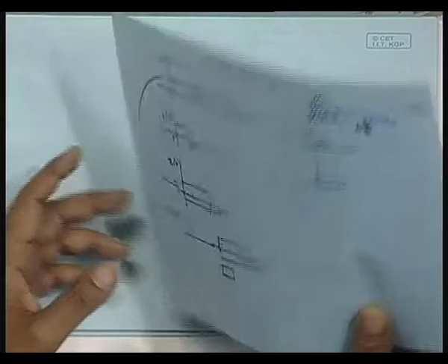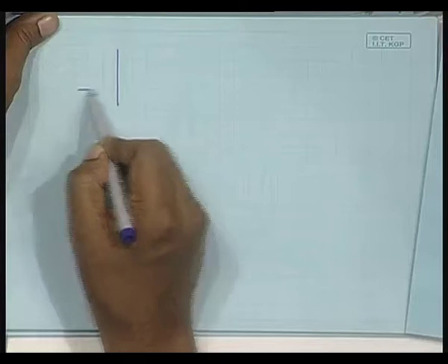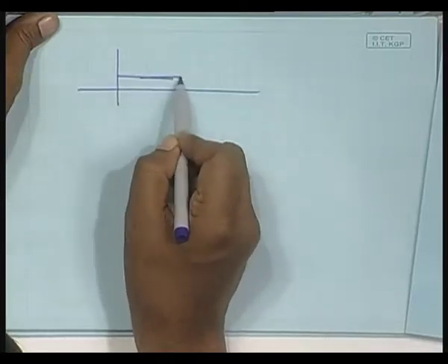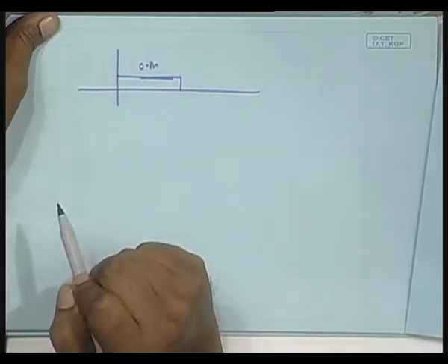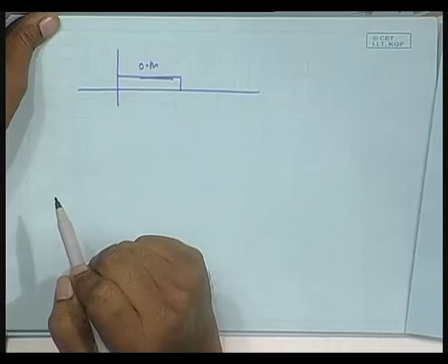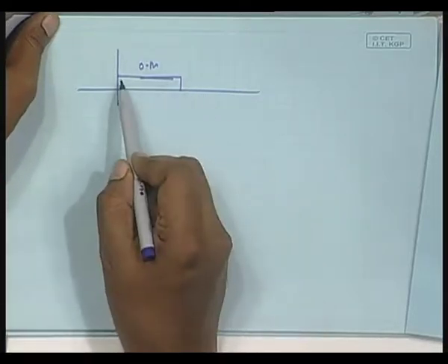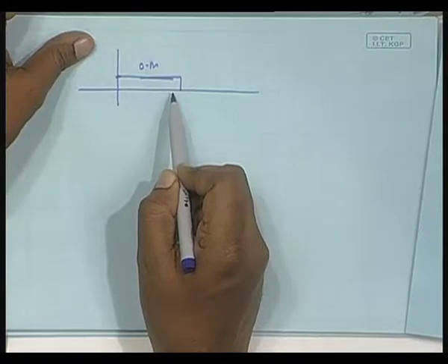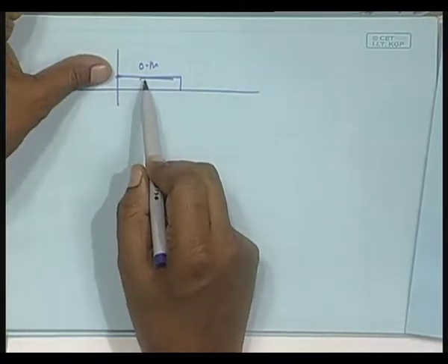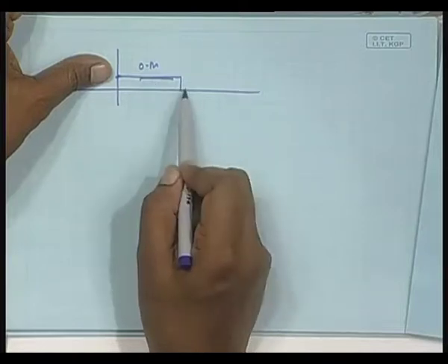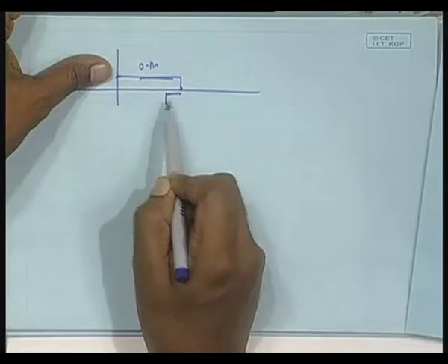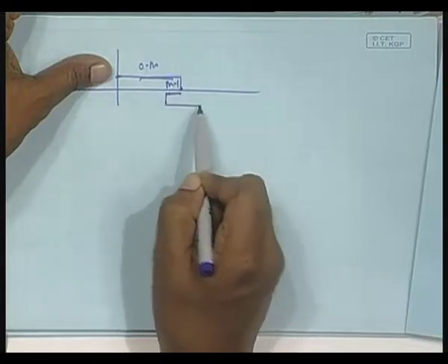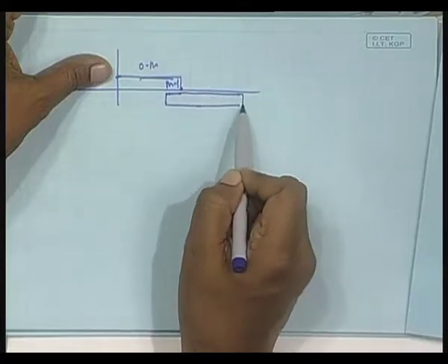Now, I propose a technique to carry out this long convolution. Suppose I break this data like this, I will have an overlap. This is my 0th block. Next block, in the case of the block adaptive filter, this will be that block by the way. Instead of starting here, I come back M minus 1 points inside and go like this.